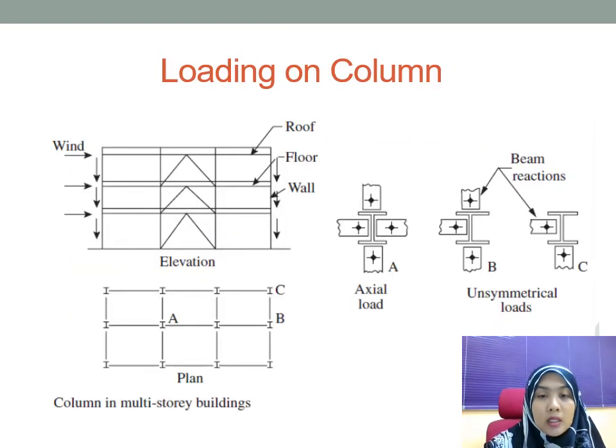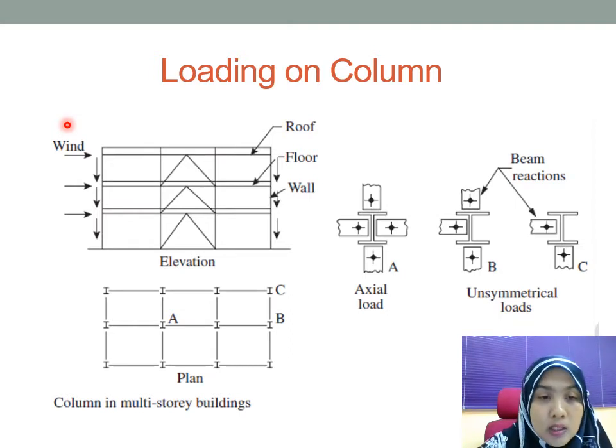First of all, we need to identify the total axial forces acting on the column, so you need to look into loading on the column. Here are some of the loadings that you need to consider in column design: for example, wind load, roof loading, floor loading, and also wall loading.